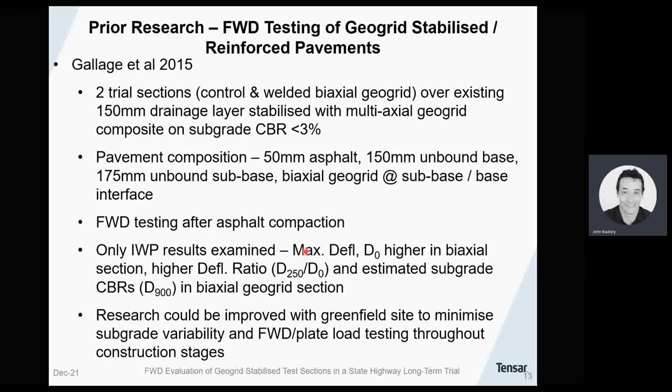Improvements to this research were stated, that selection of a greenfield site would have been preferred, with more consistent subgrade and moisture conditions to reduce variability of performance. Additional FWD or plate load testing throughout construction was suggested to provide more deflection data on the various pavement layers.